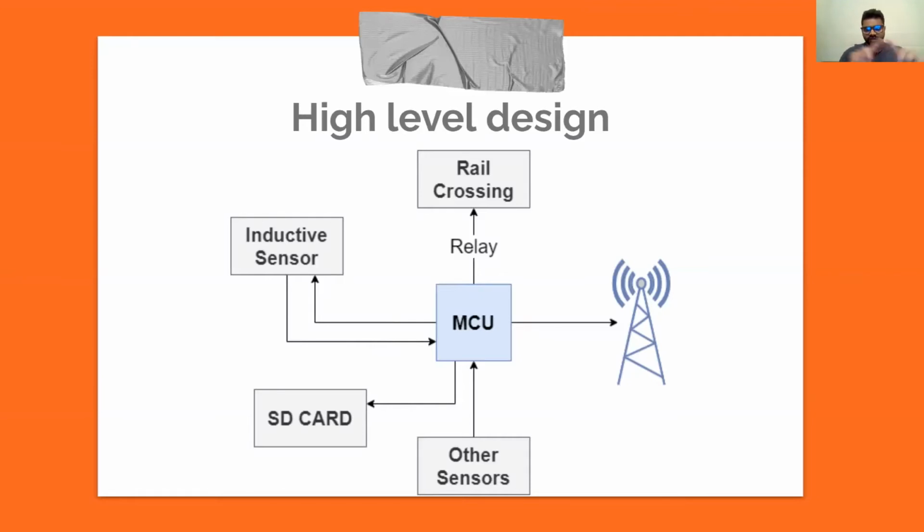So we have a while(1) loop, and inside that loop we have all our code, which gets executed over and over again. That is one of the most common ways that we implement firmware in a microcontroller.